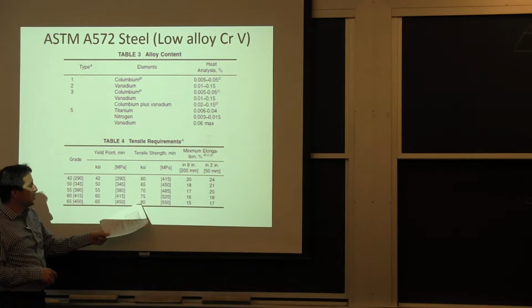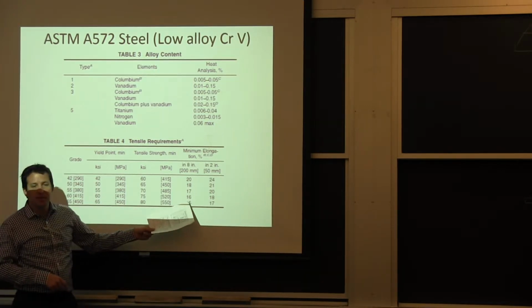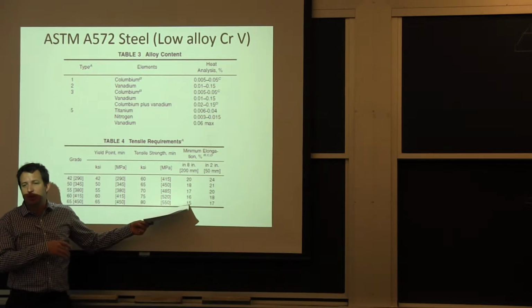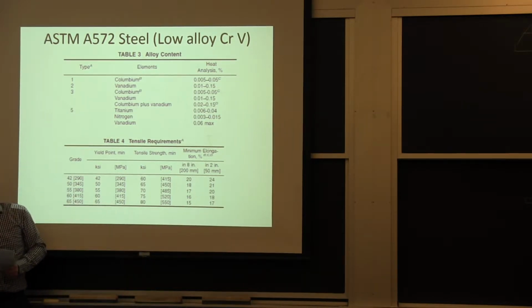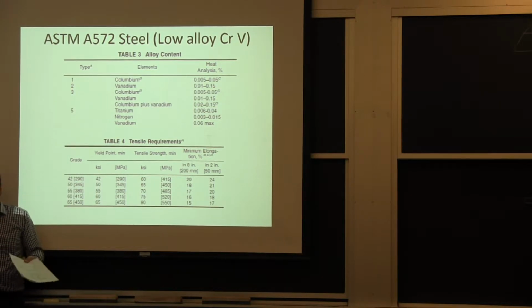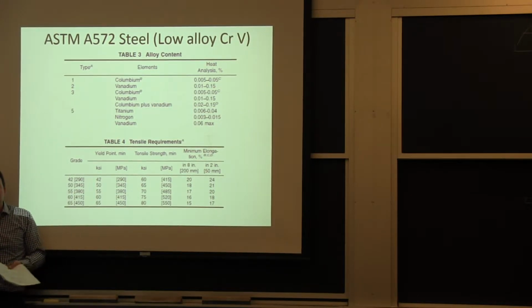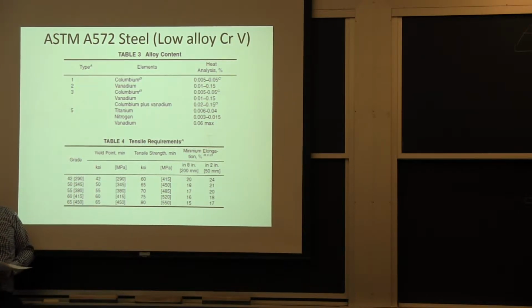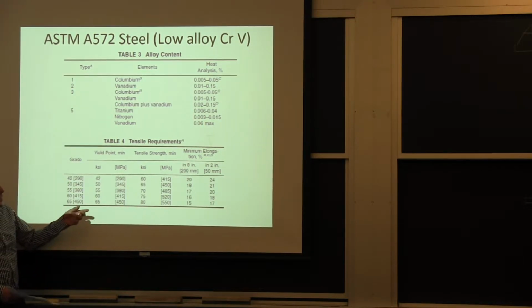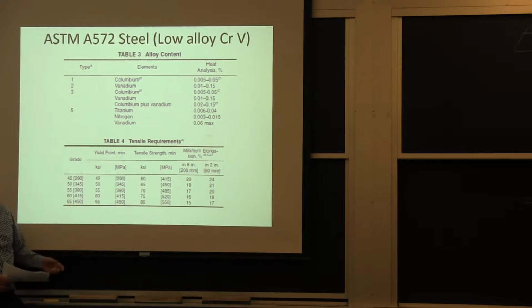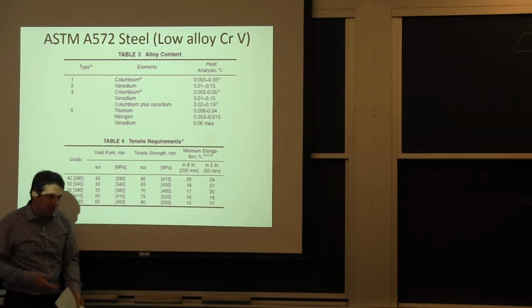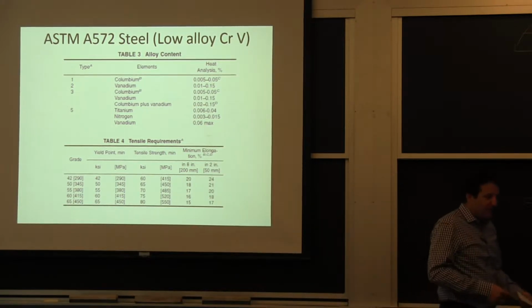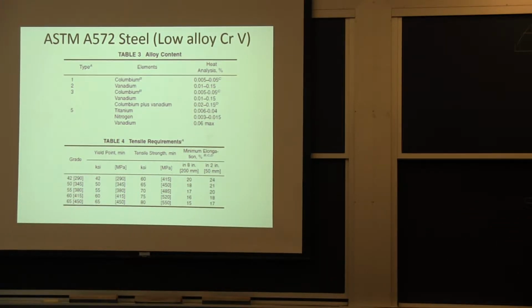One of the reasons for, at this point, not putting a maximum is that if you want to be able to get these minimum elongations with this chemistry, you can't go too high in terms of cold drawing and cold working the material. Your material can't be fully cold worked, because otherwise you won't have enough strain hardening to get this elongation and break. So it's self-controlled, but in general terms, we call these performance-based specs, because I can go to the mill and pick my temperature, pick my drawing ratios, my rolling ratios, as long as I have the chemistry and I meet these mechanical requirements, and I don't have big anomalies.